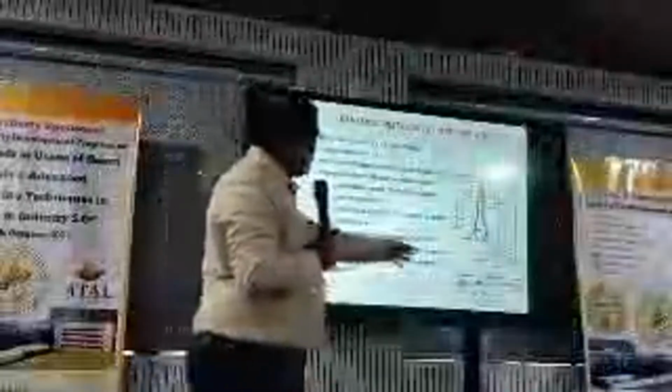And this is the phase diagram. The same transmissibility has a phase diagram, showing how the phase changes from positive to negative. This curve starts from transmissibility one, as I explained. This is called the amplification zone and this is called the isolation zone. In the amplification zone the vibration amplitude increases; in the isolation zone the amplitude reduces. So this is our linear classification.